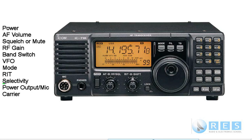Selectivity. Selectivity is the ability of a receiver to reject unwanted signals and just receive the wanted signal. To be able to make a receiver more selective, radio amateurs generally have to have filters installed in the receiver.